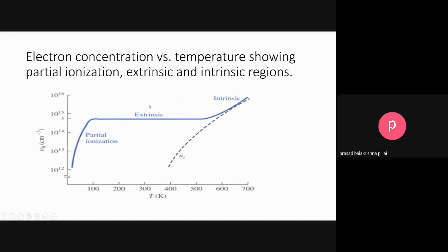Here most of the impurities are ionized, so there is no net variation in the carrier concentration. And then you have the normal intrinsic semiconductor, with carrier excitation with the temperature, room temperature and above. There will be a slight overlap here, because about room temperature the intrinsic behavior starts dominating.